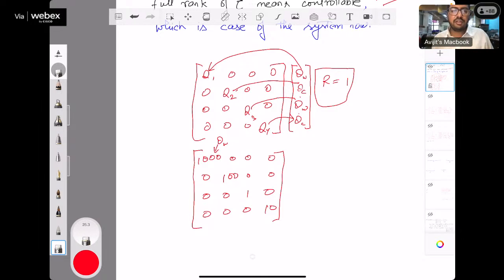That means the controller will try to restrict the change in theta W the most. It will pose the maximum restriction on theta W, and further theta C after that. Through these weights, we tell the system which of these states are dearest to me, which I want to keep constant at the reference value, 0.